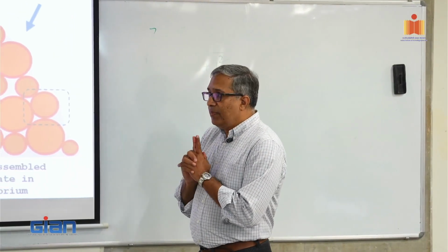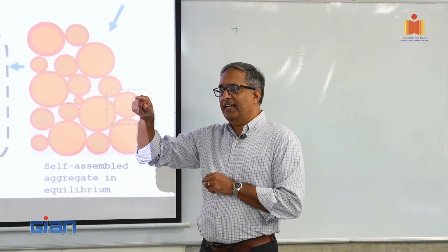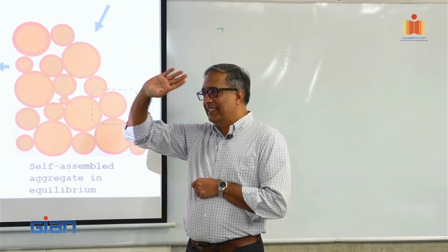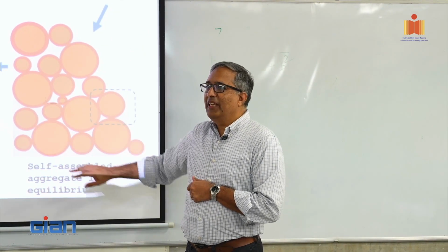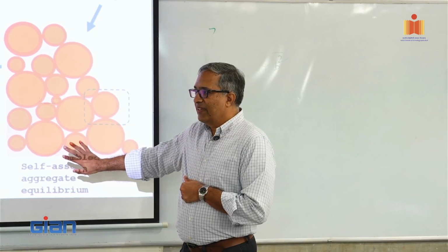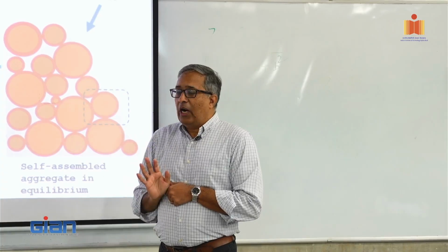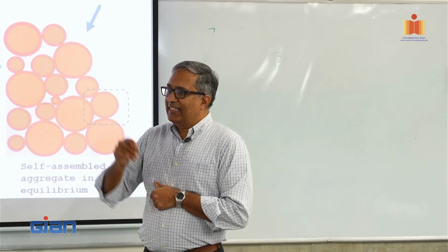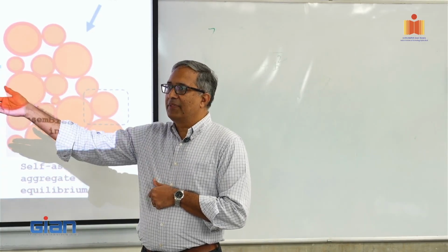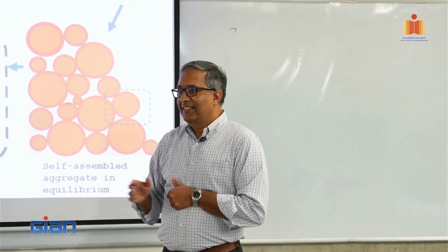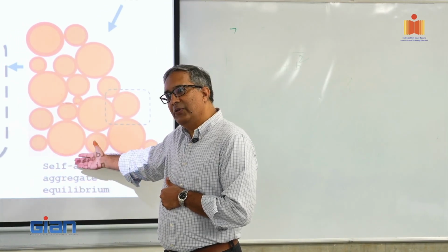Remember the three boxes that we had? The very first one was strength and durability. That was for hardened concrete. That is never to be compromised. This is the flow behavior, so whatever I do here should not affect that. Remember, how do I grade my concrete? It's in some M gradation, isn't it? M30, M35. That is strength, 28-day hardened strength. These are the games that I play when it is fluid, when it is plastic.